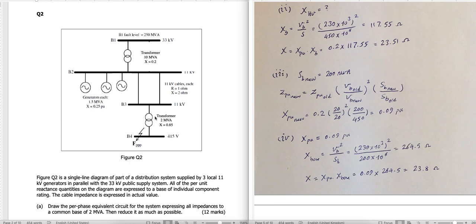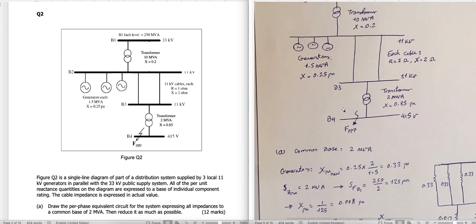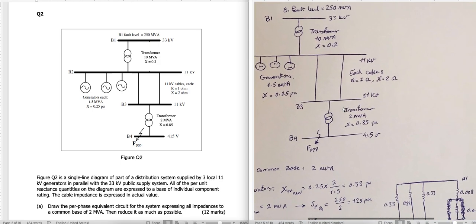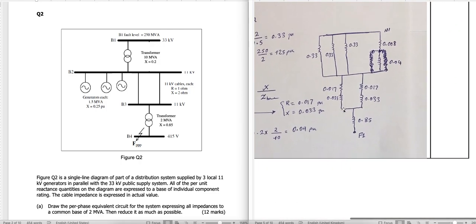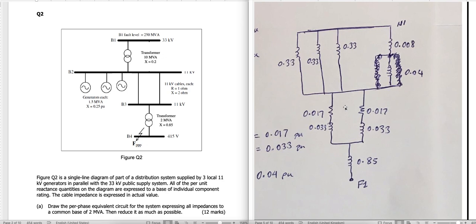As usual, we need to define the fault level of the coupling point with the upstream network. You know that this is modeled as a series reactance in the system. So when you go to map it, this fault level is mapped as an X always. The first thing, you draw the neutral line or reference line, ground, whatever, on top. You can draw it anywhere you like, but it's easier on top. Then the first reactance is that X, representing this fault level. We will see how to calculate it. The next one is this bus, B1.